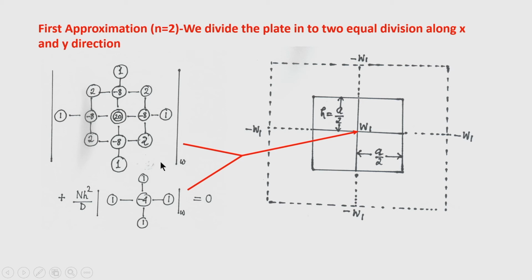of the buckling equation, because of the del square w by del x square plus del square w by del y square, these two terms are there. So, we have written these two quantities in finite difference form: 1, minus 4, 1, 1 and 1. Okay.